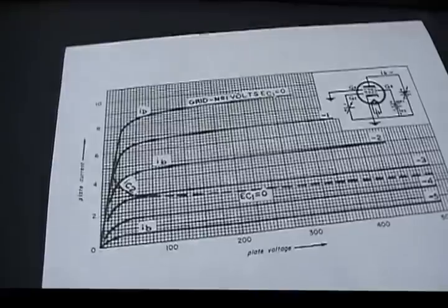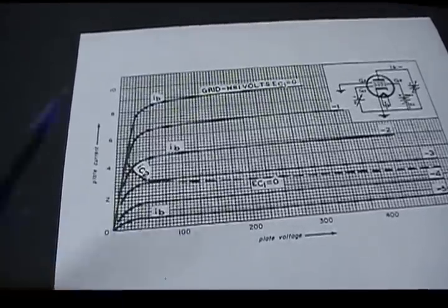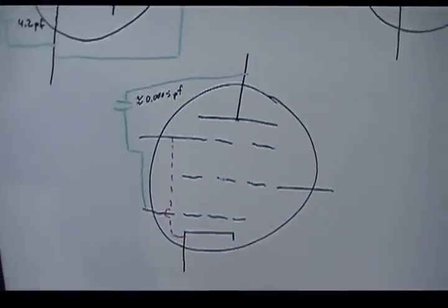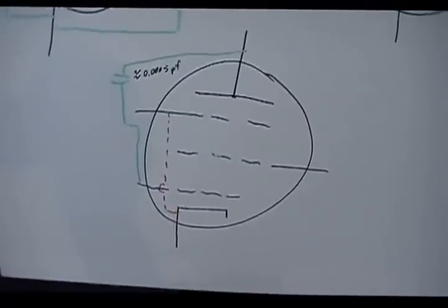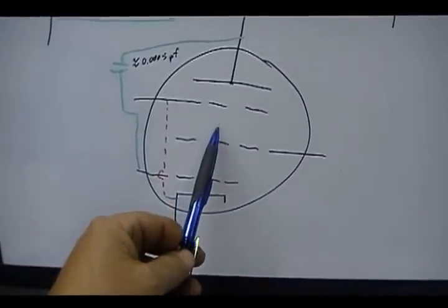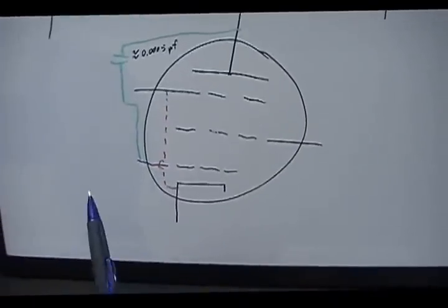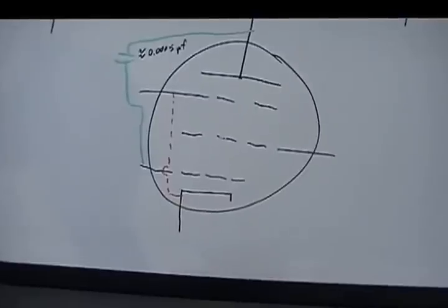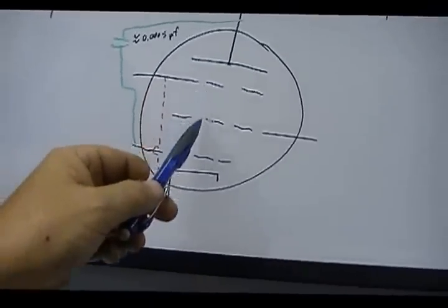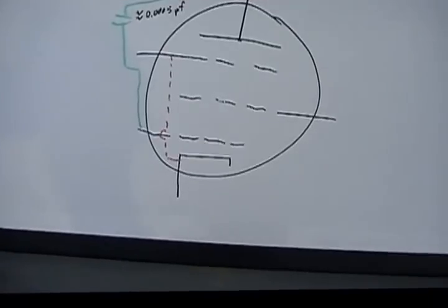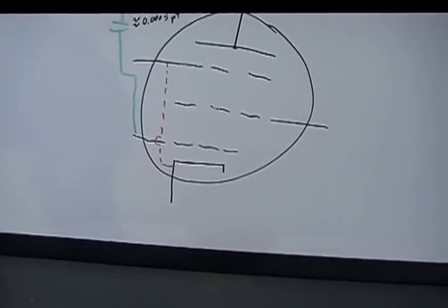Now these tubes are not much different than the triode, although their mu's can change just a slight bit, but they stay fairly stable, just like the triode under normal operating conditions. So if it got real high mu, then something somewhere has to shift. And where that shift is due to the extra grids and everything, it actually increased the plate resistance, the transconductance went down.